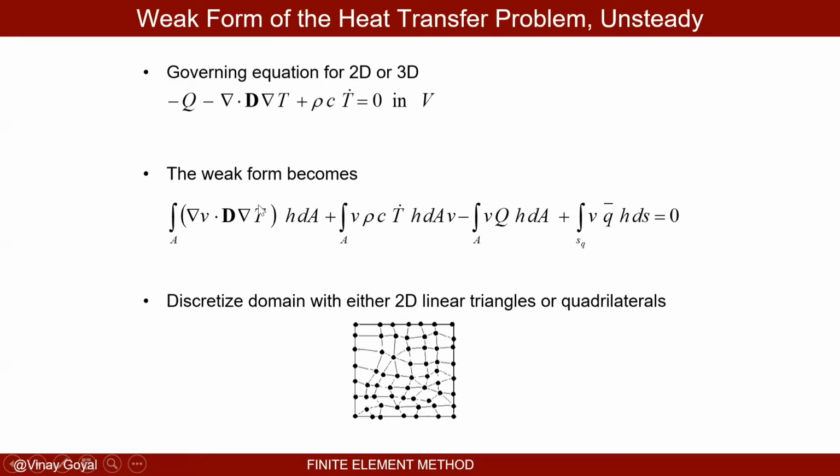The weak form is going to be this, and we derived that already. Now this V doesn't go there, I apologize. But the way you do that, you take this residual, multiply by the weight function V, integrate over the domain, so you can get an error over the domain in an average sense. And so from there, you can integrate by parts to get this expression, which we derived in the very previous lecture.